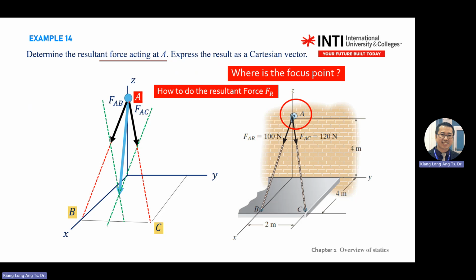The blue color is your resultant. So from this diagram, you know how to assemble a triangular vector, right? A is your starting point. This is the end point, the blue color arrow. So you pull your FAC over here, or you put your FAB over here. Same. Okay. Then in your diagram, start to use resultant F sub capital R.